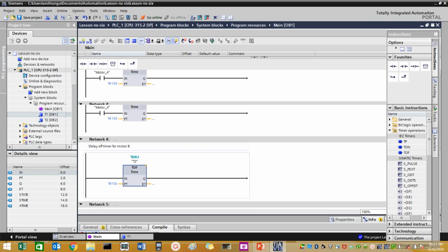If it was a normally open contact, it will go immediately to normally closed contact. If it was a normally closed contact, it will change immediately to normally open contact. Okay, then it will hold like that. So now as soon as you remove power from this relay, it will start counting to go back to the initial state. That's how it works.